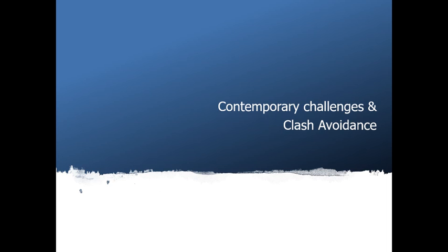Then someone involved in shared uses design collaboration to aggregate the models, do clash detection, and send the report back. So before you move from one version to another, you make sure that the version is clash free. At the end, you will end up with very minimal clashes. So the workload will be less for the coordinator, which means there's a higher chance that your model will be 100% accurate during construction.